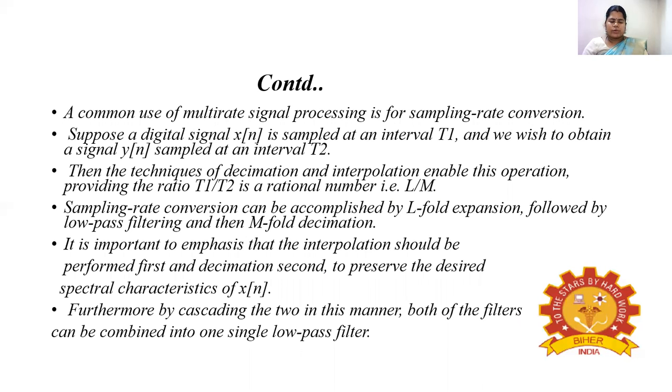It is important to emphasize that the interpolation should be performed first and the decimation second, in order to preserve the distinct spectral characteristics of the original signal. Furthermore, by cascading the two in this manner, both of the filters can be combined into one single low-pass filter.